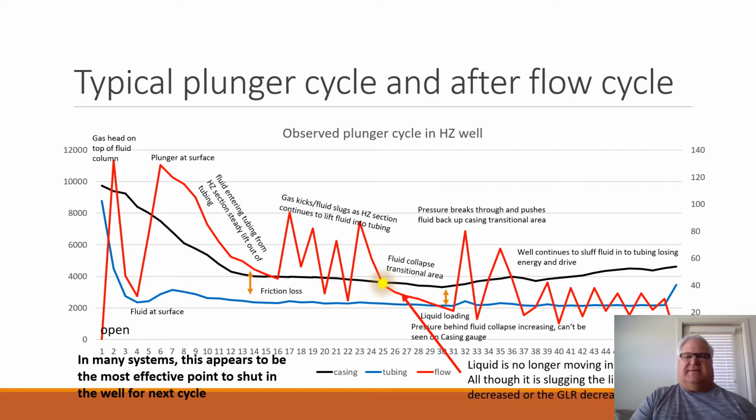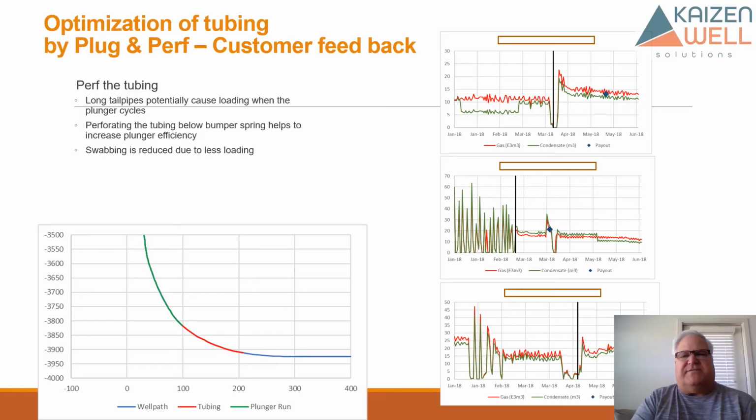So lots of times you'll see a conventional plunger cycling once or twice a day just to really kick that fluid up when you're well above critical rate. And then you'll move to a two piece free cycle when you're really needing to move lots of fluid with the plunger and it needs to do more of the work. And then you'll slowly, as that well loses the drive and the energy, see it switch back to a solid type plunger again. So there's multiple stages through the life of these plunger lift wells.